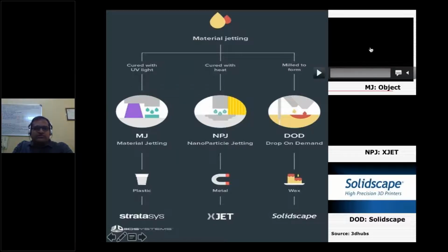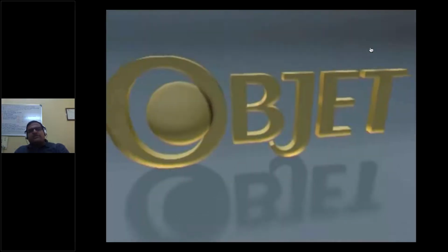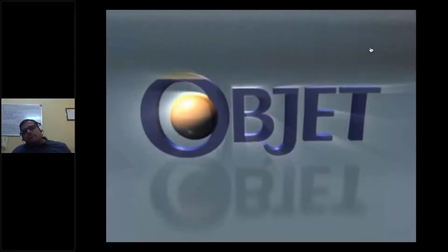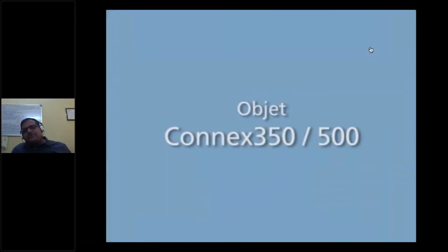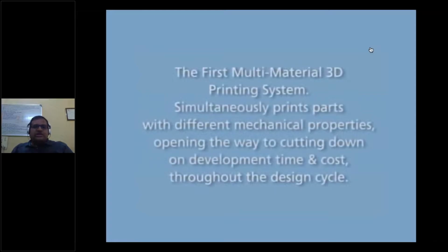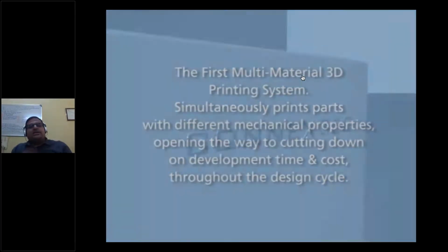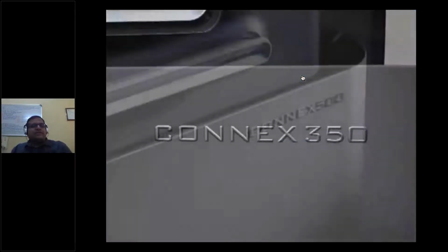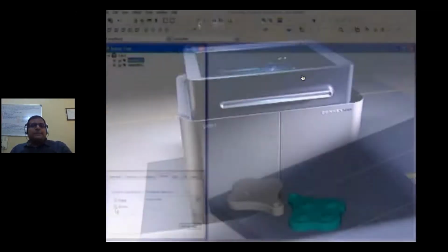You can very well demonstrate this through this video. You start with the same raw material, but don't pour it into a vat, you jet from the nozzle like your inkjet printer. So here you have an advantage of jetting it. Why? Because you can dedicate some of the nozzles to one material and another row of nozzles to the other material. So there is a provision here.